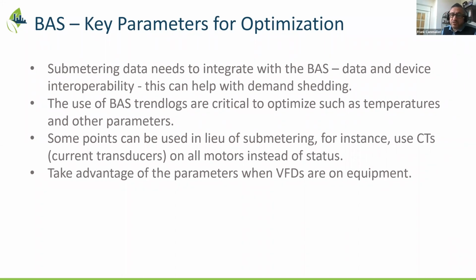And so, you would need to know, okay, why is the compressor acting the way it is? Why are the condenser fans running the way that they are? That involves more than just capturing the energy. This is where the BAS and the use of trend logs of other parameters that motivate, and are the catalyst for, the way the equipment operates is essential. That gives you that layer deeper.